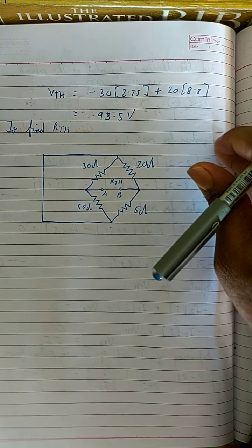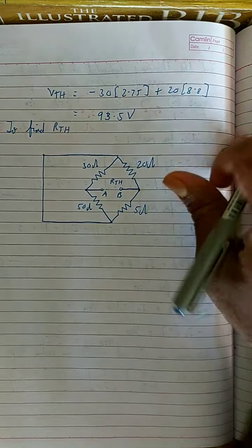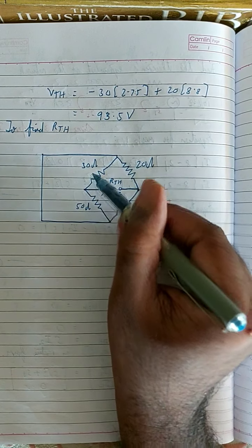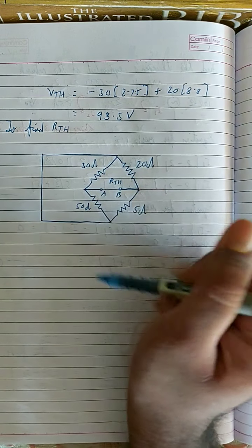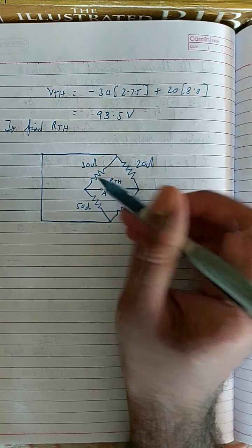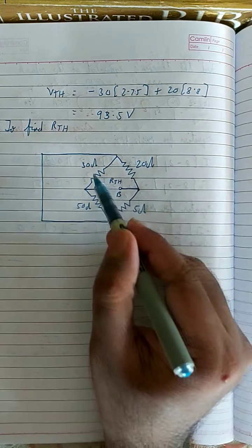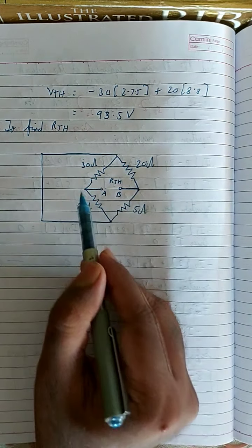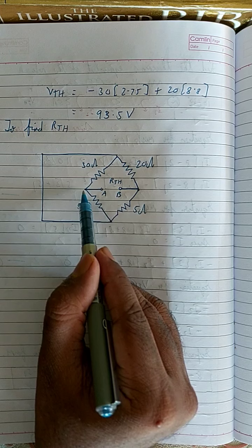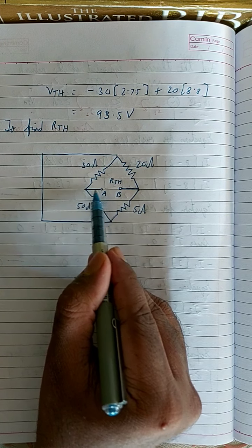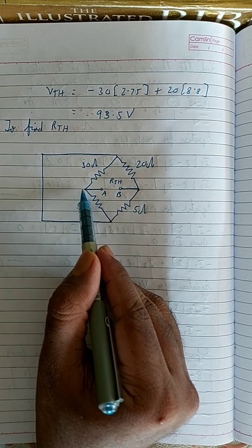So here, let me see, how do you want to find it? Suppose if you look over here, these two resistors are in parallel to each other, right? Try to simplify the circuit. How do I know they are parallel to each other? Because if you look at these two resistors, their endpoints are the same. That is, one endpoint is attached to terminal A, so one junction is exactly the same. It is connected to A. And what about the other end of the resistor?